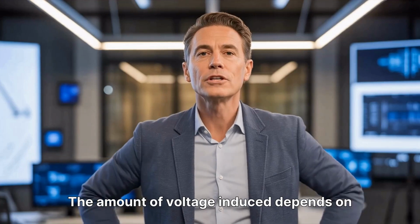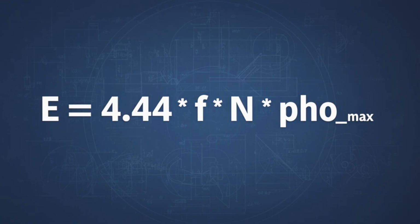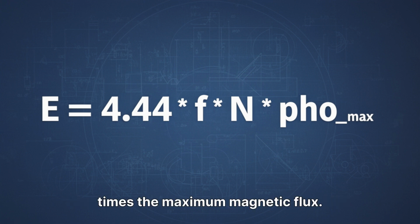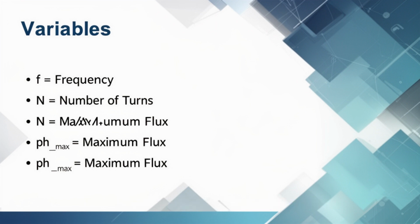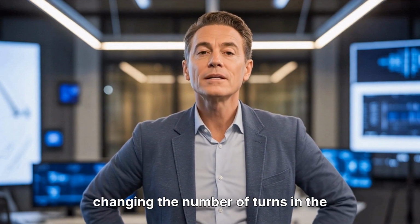The amount of voltage induced depends on two things: the rate of change of the flux, frequency, and the number of turns in the coil. Mathematically, the induced EMF, E, is 4.44 times frequency times the number of turns times the maximum magnetic flux, where f is the frequency in hertz, N is the number of turns, and phi max is the maximum magnetic flux. This equation tells us something powerful. We can control the output voltage simply by changing the number of turns in the coils.